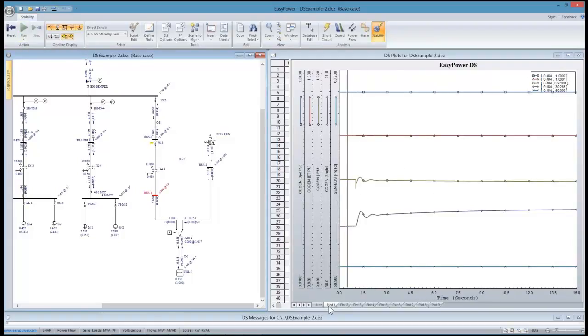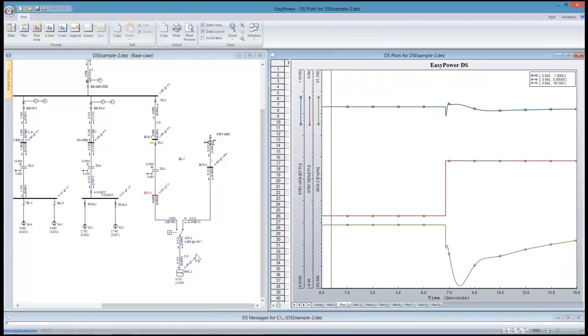Okay, we can see on plot 1, which is the cogen, that there was a minor perturbation, but because we didn't lose much load, it didn't suffer much. But on plot 2, which was the bus on the standby generator, as the ATS switched over, we're looking at the standby generator current, voltage, and frequency. As it picked up the load, its frequency dropped to 59.331 and then recovered. And you can see that the frequency and the voltage responded to that change in load.